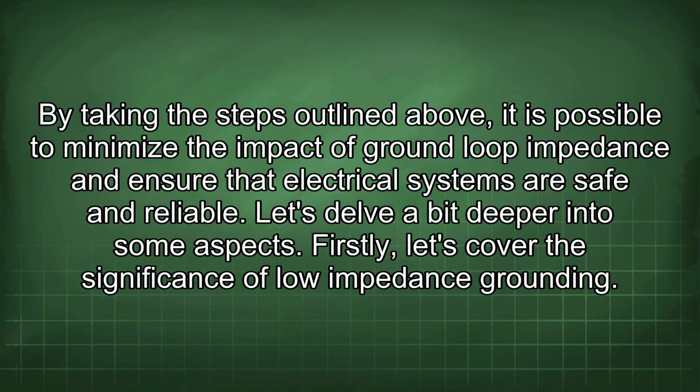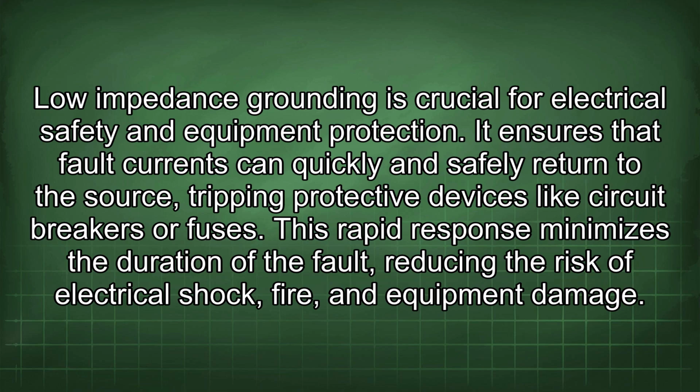Let's delve a bit deeper into some aspects. Firstly, let's cover the significance of low impedance grounding. Low impedance grounding is crucial for electrical safety and equipment protection. It ensures that fault currents can quickly and safely return to the source, tripping protective devices like circuit breakers or fuses. This rapid response minimizes the duration of the fault, reducing the risk of electrical shock, fire, and equipment damage.